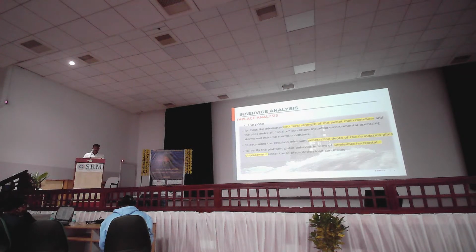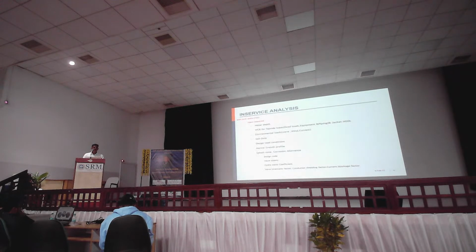So here again we have to design our pile penetration. How much do we need to penetrate? What is the diameter of the pile? All this we can finalize after this in-place analysis. So we need to consider the water depth and proper weight. A weight control report is a must for this offshore platform. And environmental conditions: wave, wind, everything.